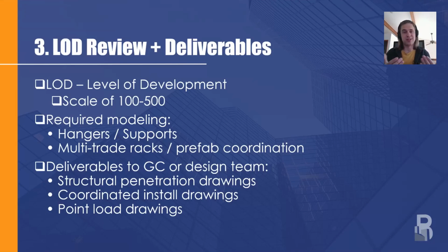While penetrations are generally coordinated during the design phase, this gives the design team a chance to see a coordinated set of penetrations that are going out there. This is huge, particularly when we're talking about a post-tension structure, and getting all of those penetrations coordinated with the concrete reinforcement and the PT contractor, or precast, also very important there.